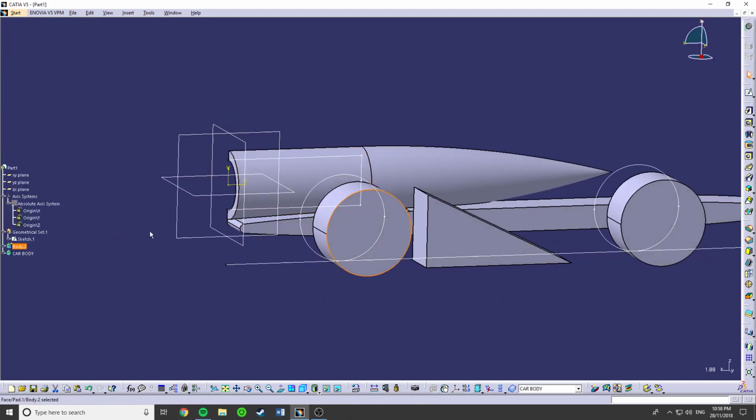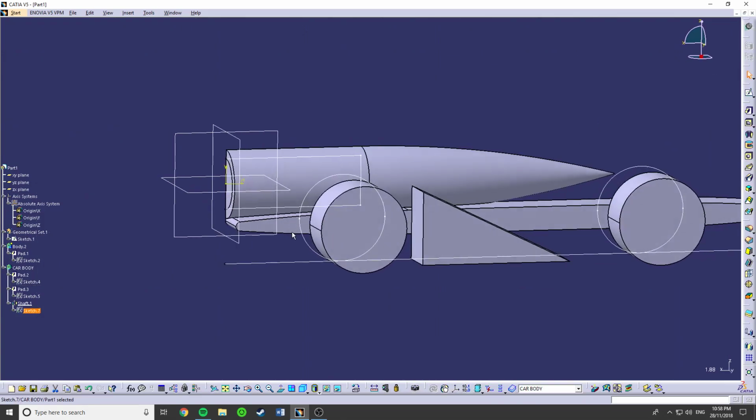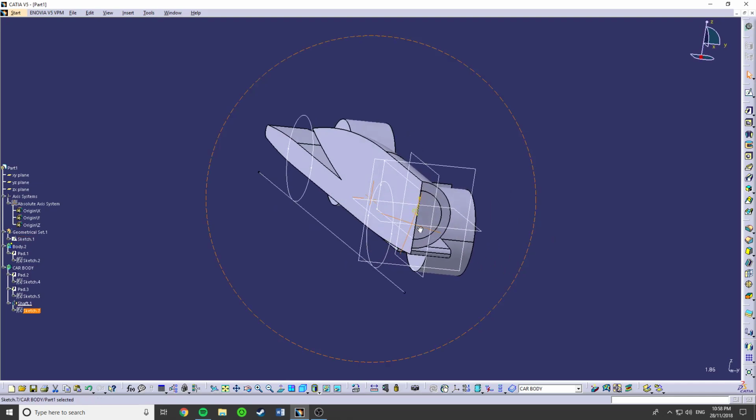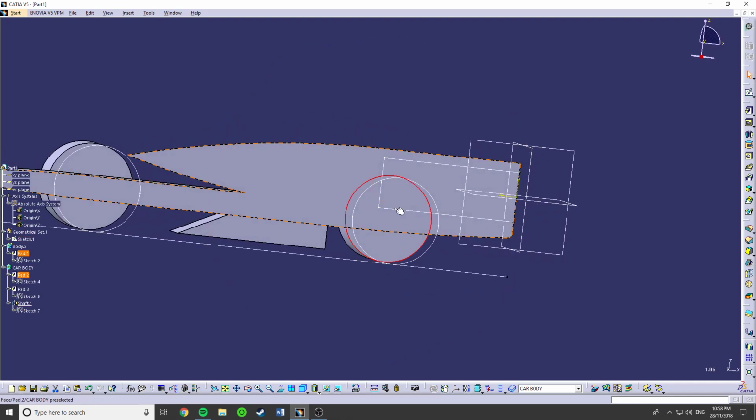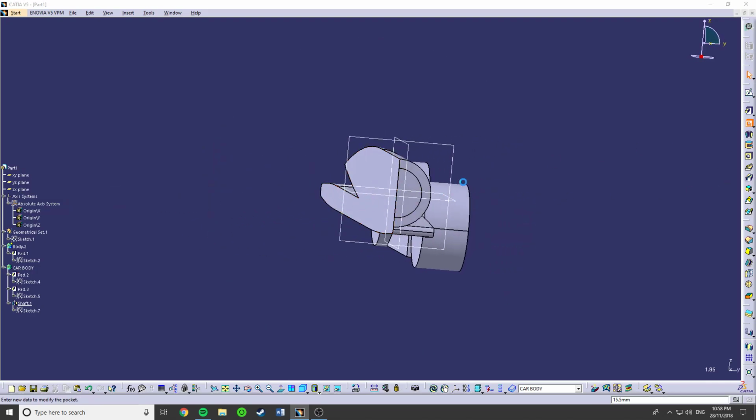You can also create your chamber using the pocket tool. If I go back into this, sorry, and delete the whole thing, and then just go straight down. Obviously it should be constrained, make sure you constrain it. And obviously there is no hole in the part, it's all still there.